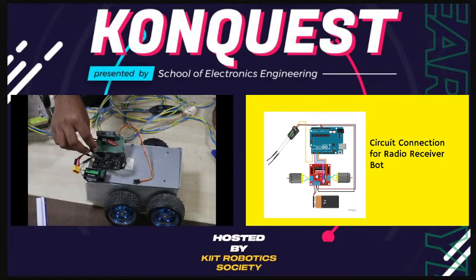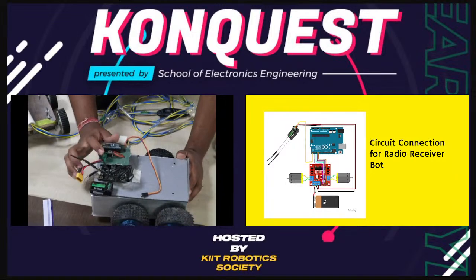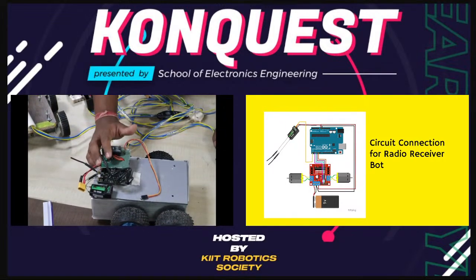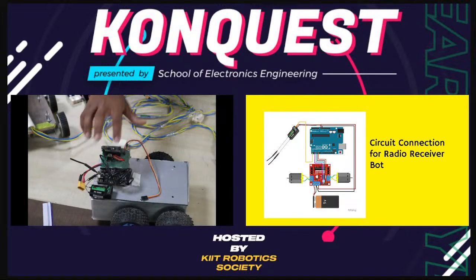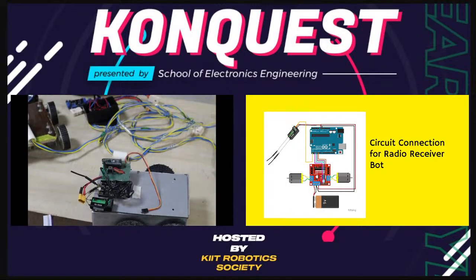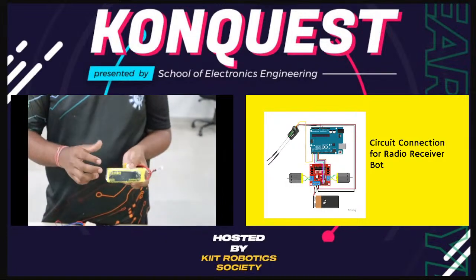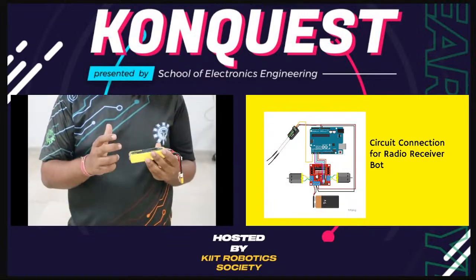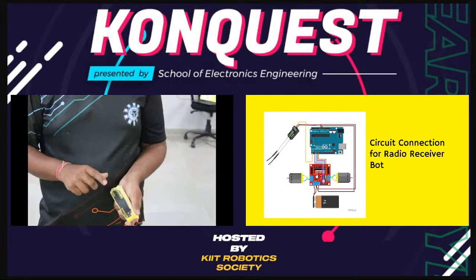Now, this part here, if you are able to see, is a small chip type of thing. It's like a BJT or MOSFET, but it's actually neither a BJT nor a MOSFET. It's a voltage regulator. Now, why are we using it? For the power supply, in most of our cases we are going to use these kinds of batteries. These are LiPo batteries, 3S, like 12 volt LiPo batteries with about 2200 mAh.